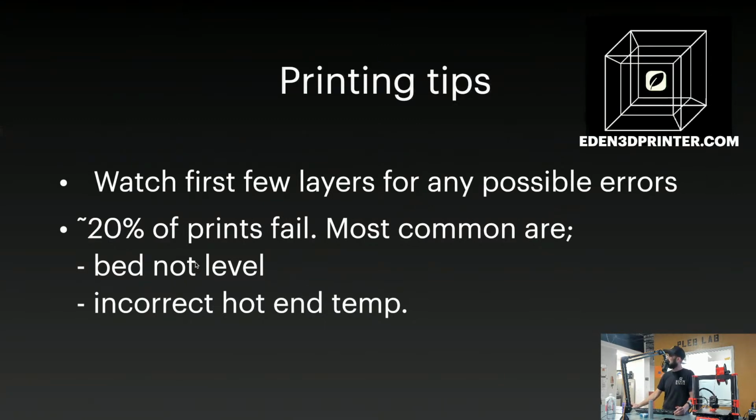Kind of one of the last things, and we just said it before, the bed is not level. That could be one of the major problems, even if it's slightly off. Auto bed leveling helps, like a BLTouch. Prusa has their PINDA and other auto leveling systems. Others have theirs as well. Vorons, we used to do the Klicky Probe, and there are many other variations. But the software and hardware integrations have gotten better over the years to compensate for these issues.